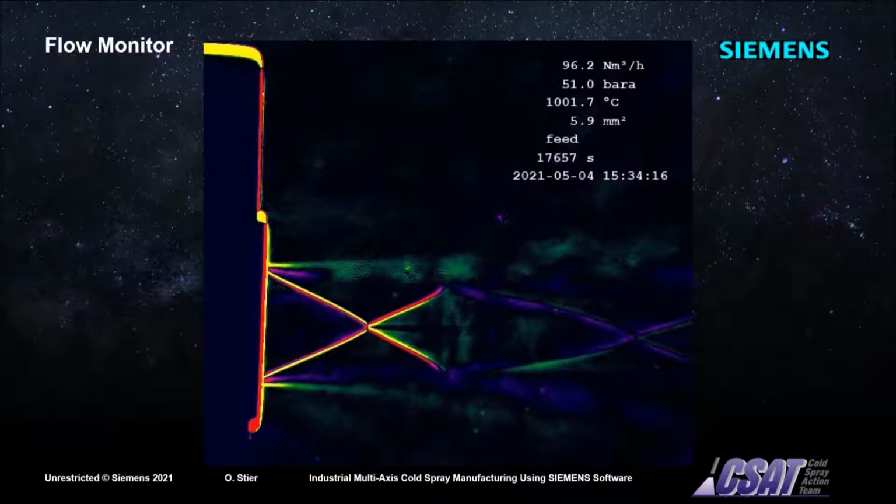Powder particles randomly striking the nozzle wall in the divergent section little by little form an internal coating, gradually increasing the wall roughness. The roughness continues to grow in a stochastic manner until a few nucleation sites form which efficiently capture impinging particles at increasing rates.